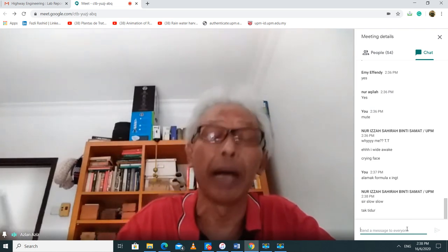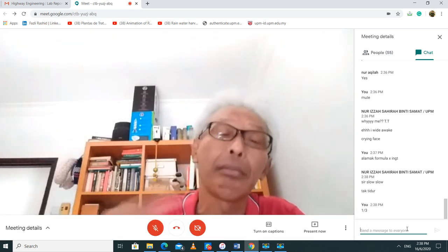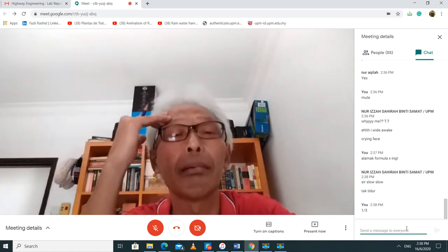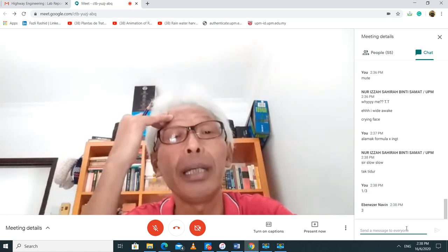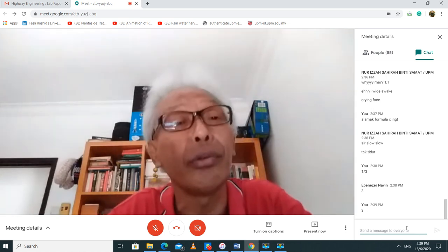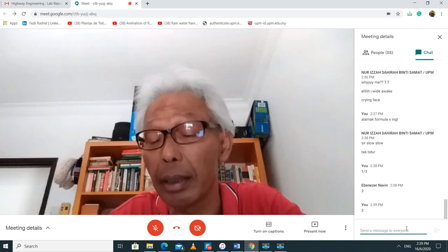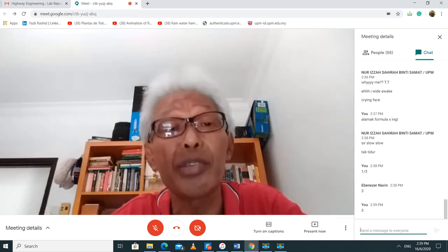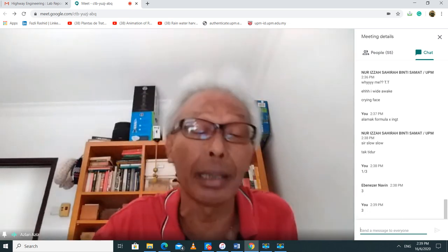KA is equal to 1/3. Good, Fazli. So KP, no need to calculate, just look and you know already. KP is 3. So now imagine if phi is 30 degrees, KA gives you 1/3, KP equals 3. So KP is always bigger than KA.